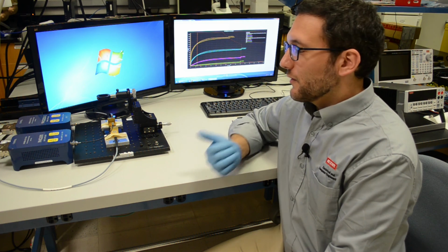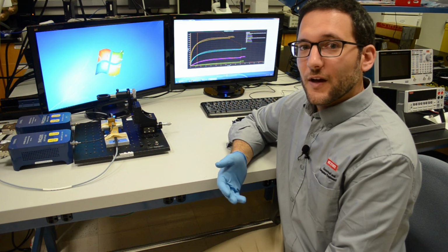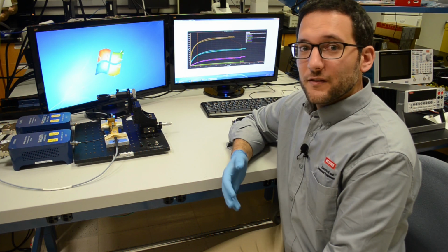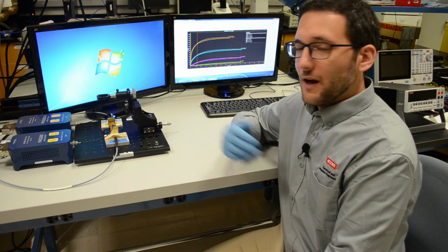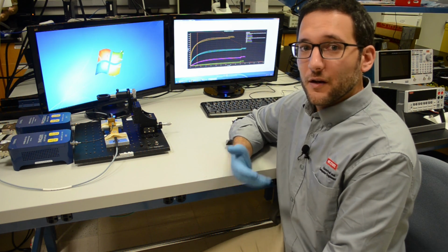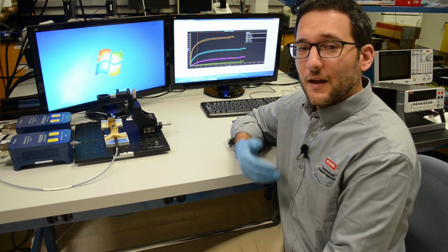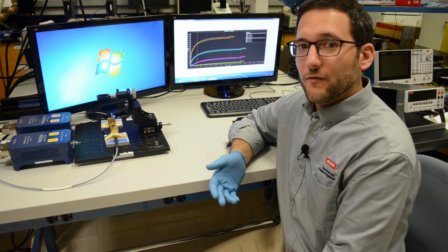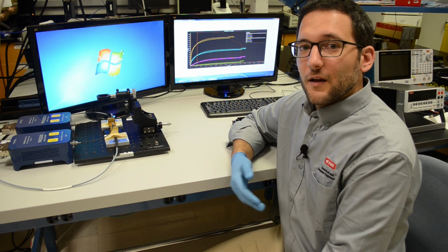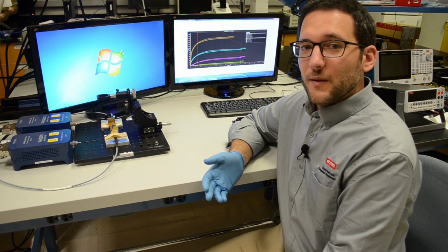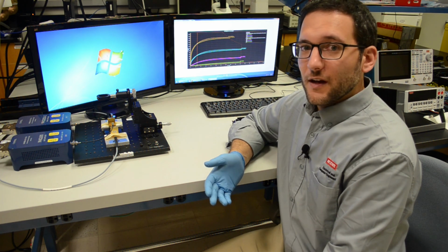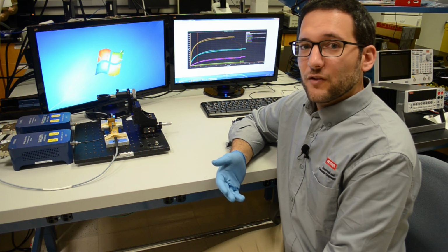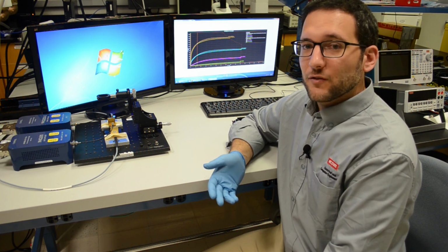After that, we came over here and we took a look at this pulsed IV system, which allows us to test a packaged device. This was an AlGaN-GaN HEMT that was wire bonded on an aluminum nitride substrate. And by using these dynamic square waveforms, we can look at the dynamic behavior of a device. Once all of these characterization steps have been done and the device clears these tests, we can then proceed with packaging them inside of a commercial package.